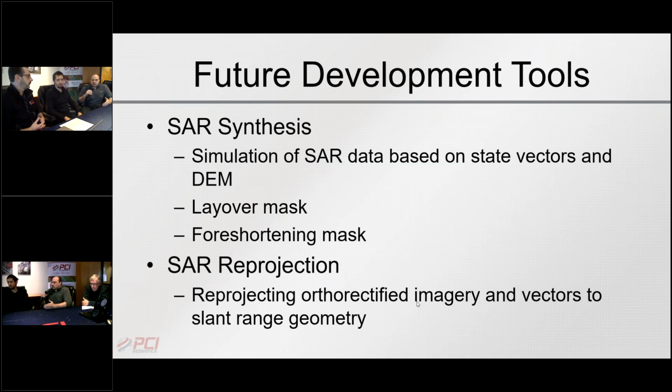And at the end, when you're doing deformation analysis, or even if you're trying to extract a DEM, we don't need full resolution most of the time. And you can also launch snafu 2 or 3 times, processing in parallel too. It's also possible. You can do it either manually, or through a script: launch snafu for your first interferogram, and launch another one, so you don't have to wait for the first one to finish.